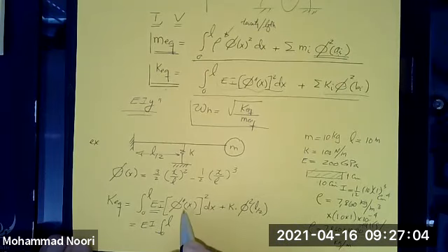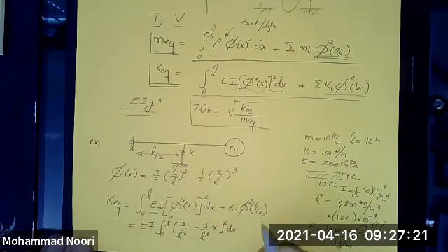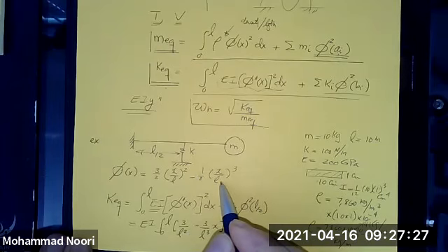If you take the second derivative of this, you see that it would be 3 over L squared minus 3 over L cubed times x. Square that, and evaluate the function at L over 2.